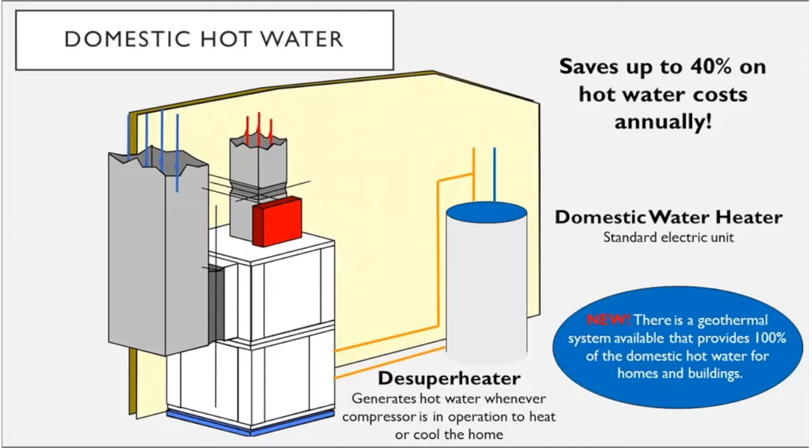Whenever we take a shower or the washing machine runs or whatever, it sucks the hot water from the hot water heater, and then it's replaced from the storage tank that has had time to circulate with the unit. So whenever the hot water heater is fed water, it's already preheated, probably upwards of 115, 120 degrees sitting in that tank, so that your hot water heater has to do minimal heating to get the domestic hot water up to temp.